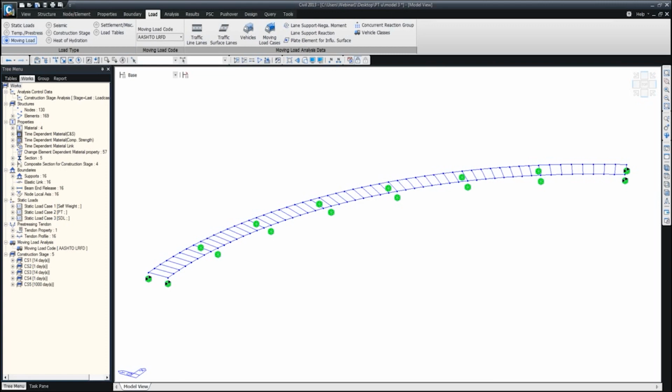Now sometimes engineers want to let the rest of the curing occur while the segment is already in place. So you can then define the age as 14 days and let the structure stay as it is for the first stage with the duration of 14. So that makes up for 28. I hope that answers your question.